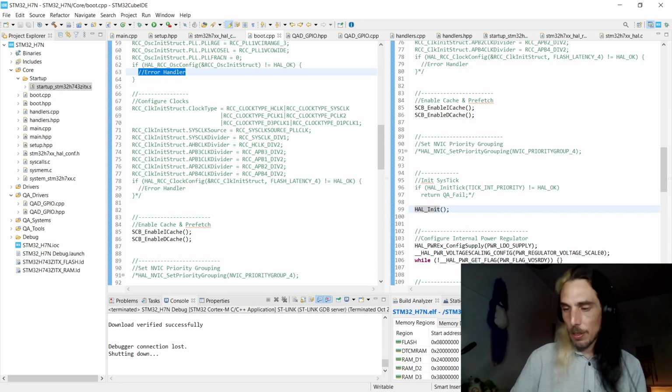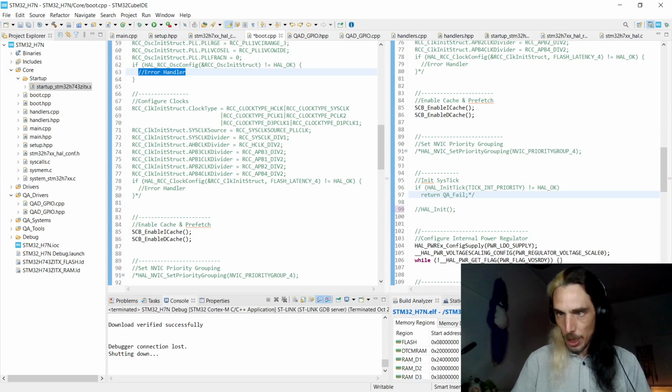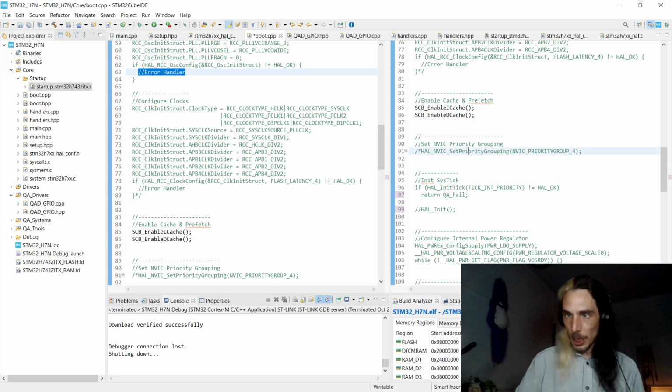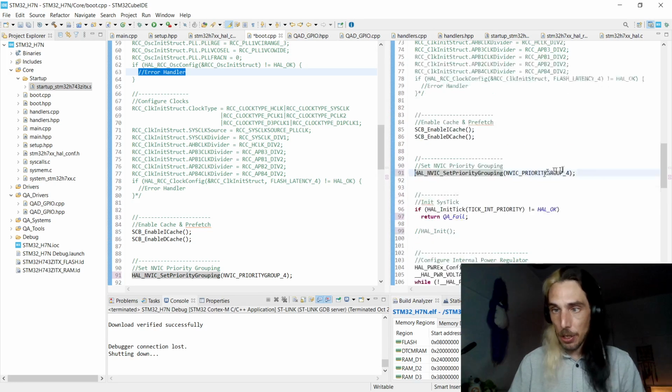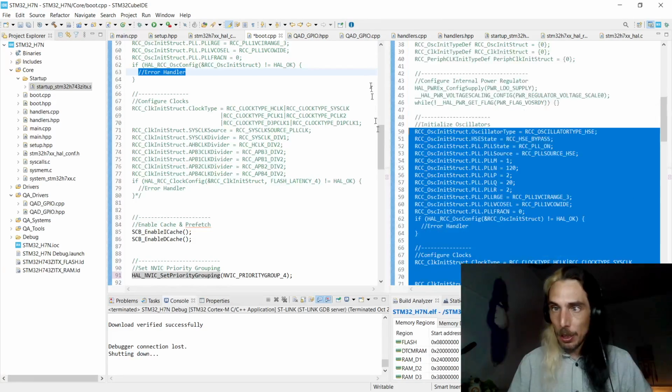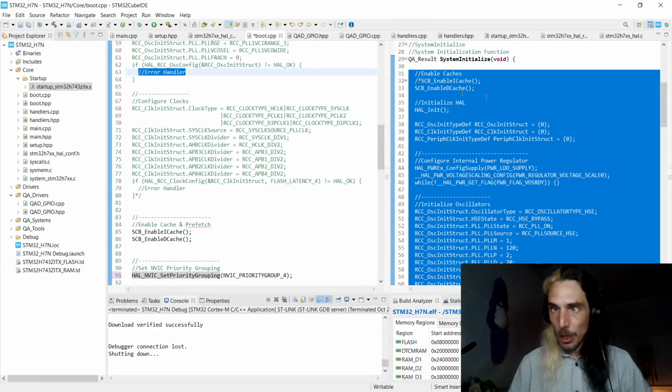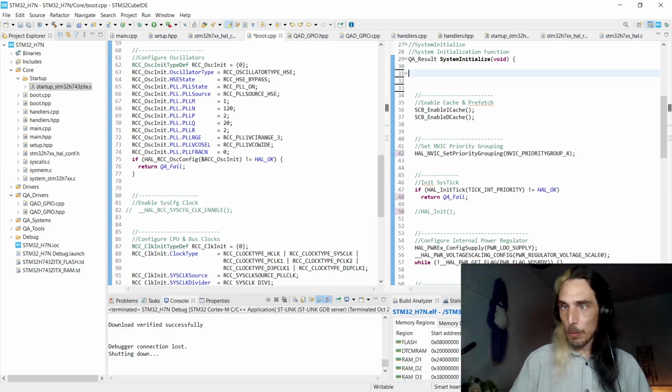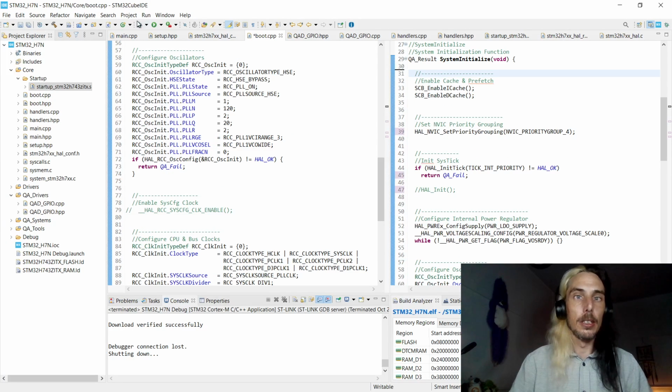And just to double check as well, let's go through and instead of using HAL init, we're going to do our NVIC priority grouping and our SysTick manually the way I wanted to do them before. We know that that code there can be removed because we don't need that now.